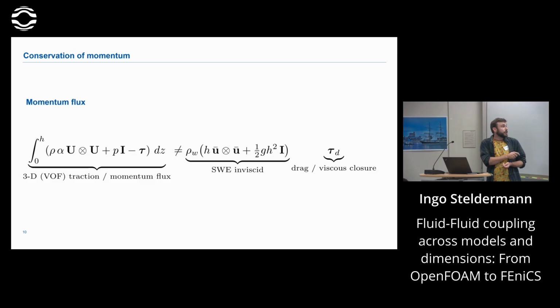And then there are other things, for example, the pressure. Here we have the pressure on the shallow flow side, which is hydrostatic. If you're non-hydrostatic, of course, we violate these, right? But I would say this one we can easily design by choosing the right interface position. This one is a little harder. And then there's the viscous stresses. This is typically the modeling task of your reduced order model. So what I'm working on is this side here. I would like to have a better model here to bridge this.